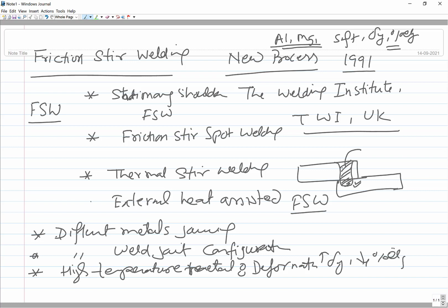So for the conditions that you need to deform metals of high yield strength and low ductility, you need to come out with further improved setup, tooling, and external sources of energy in the form of heat or some other kind that can facilitate the deformation of such high temperature metals.